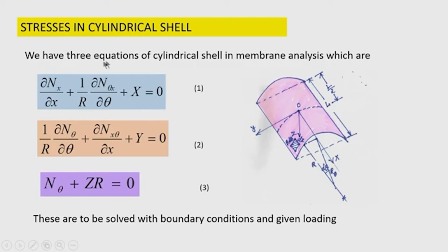Now, the equations of equilibrium in three directions have been obtained in the last class, and these equations are in this form. The first is the differential equation relating the membrane forces in the longitudinal direction, that is N x and N theta x, with the component of the load along the longitudinal direction.